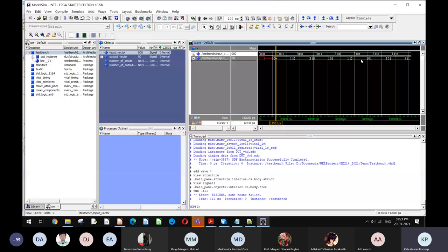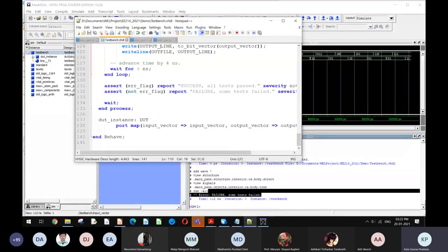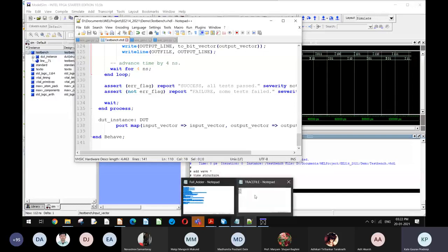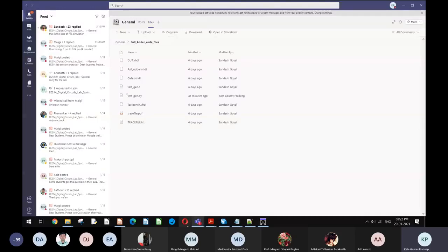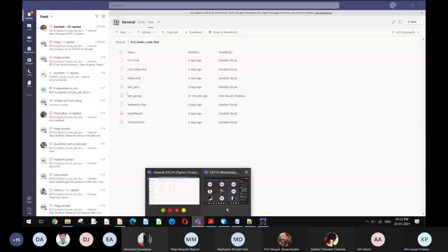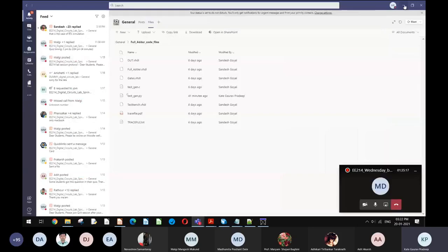And the last case that is remaining, let's say I want my test bench to ignore this error. For some reason, I don't want my test bench to look at this particular input and output pair. I want it to ignore this particular case. So for that, as we know, we can put these mask bits to 0, 0 so that it will completely ignore this case.